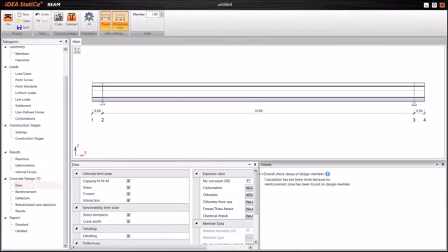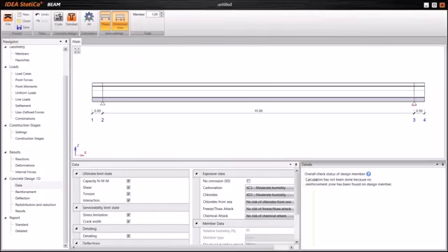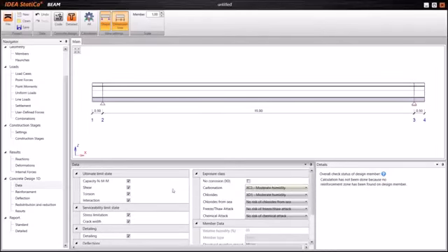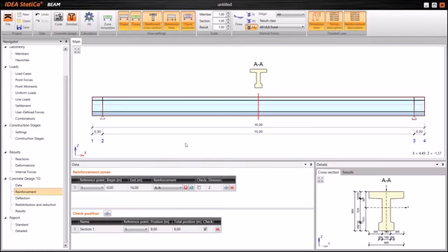First of all, we can mention that all these exposure classes and other data can be adapted. Also, checks can be selected which one we want. But we have to define reinforcement zones. For pre-tension beams, usually we have the same reinforcement along the length. Possibly the shear reinforcement above the supports will be different, but for simplicity I don't mind at the moment.